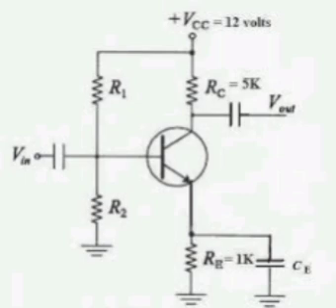Surface concentration N0 equal to 3.3 into 10 power 26 boron atoms per meter cube. NB equal to 10 power 23 atoms per meter cube. XJ equal to 2 micrometers. DB equal to 4 into 10 power minus 17 meters square per second. We know N of x comma t equal to N0 of ERFC of x by 2 root Dt, where x is the numerator and 2 root Dt is the denominator.